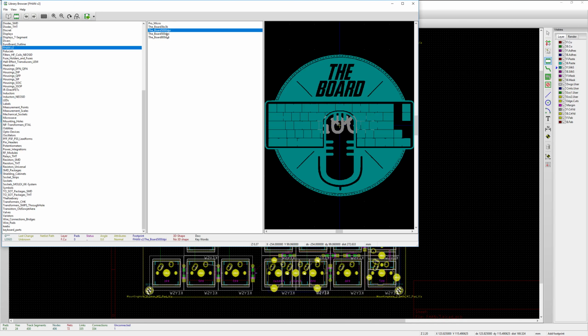Let's have a look. Is it the 800? There we go. 800 DPI, and we can put it somewhere fancy. I don't know. I could put it in the middle, but then it's just going to be a bit weird because that screw hole is going to be there. So maybe we'll just center it like that. Bam. There's our front silkscreen.